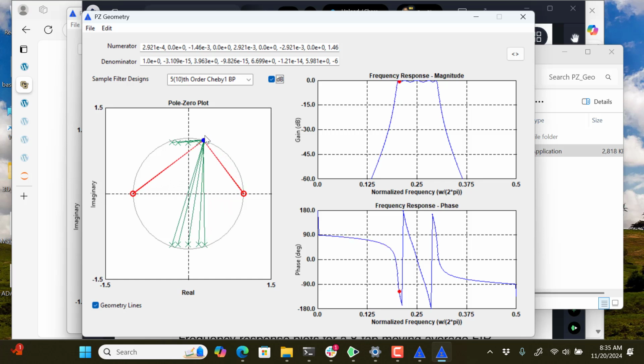And the configuration of the poles makes it, as you're zooming by, you're passing through the ripple, and the ripple is going to be controlled by the exact placement of the poles. If they're further in and more circular shape, then it has a flat response.